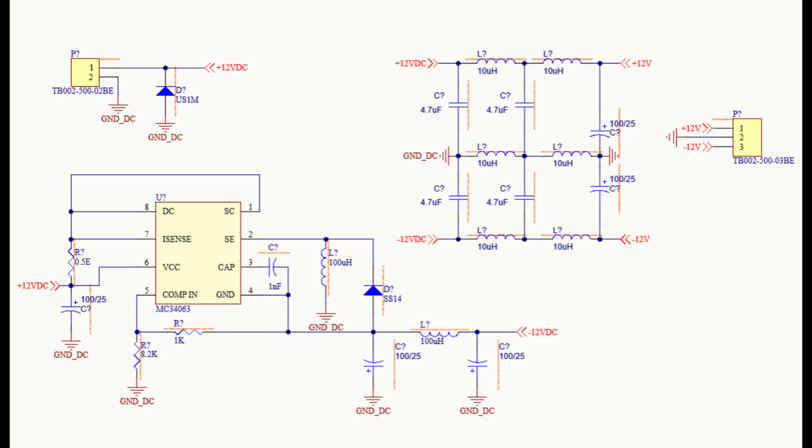Following the same procedure, the remaining components are placed and the schematic is completed. For creating electrical connections, the place wire command can be used. A faster method is the keyboard shortcut P, followed by W. Proper wiring is essential for defining correct circuit connectivity.